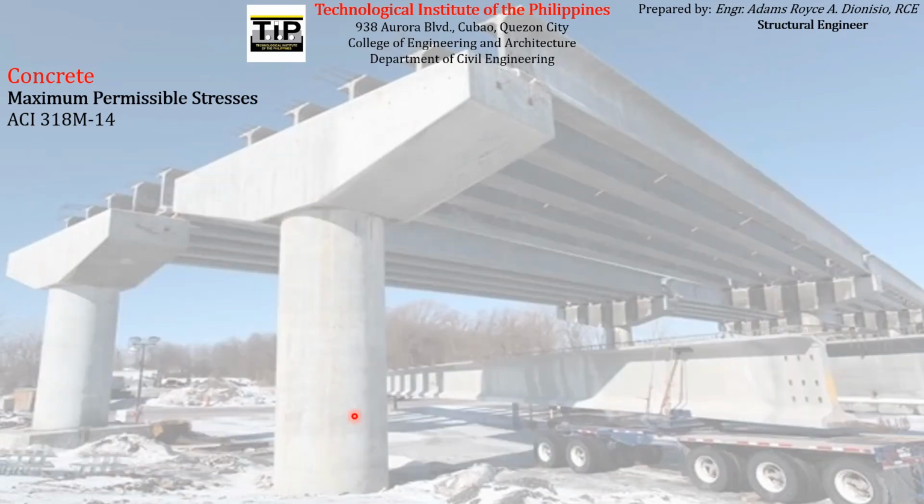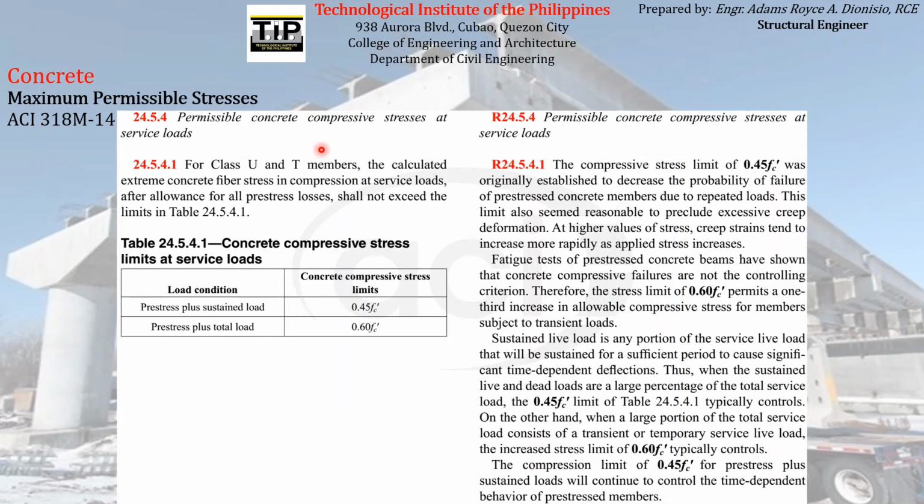But after the transfer stage, for example, when the concrete is already under service load condition, wherein it already carries the service loads that are intended to be supported by it, the code also specifies maximum compressive stresses as well as tensile stresses that the concrete can experience, to make sure that it will not be overstressed and can still serve its intended purpose, which is to resist the ultimate loads that are expected or designed to be carried by that particular concrete element. So those are from the ACI code.